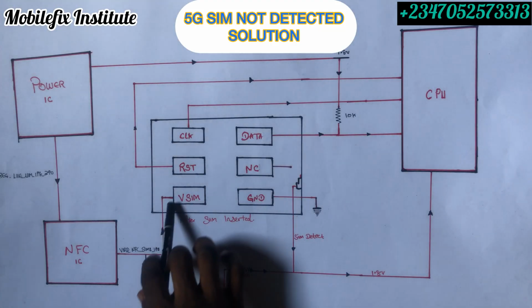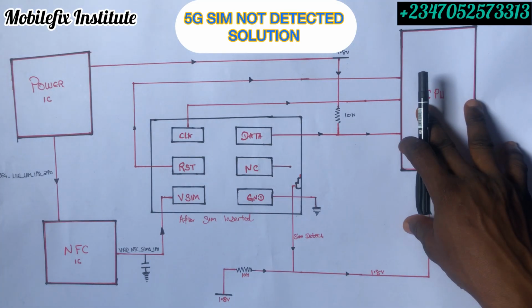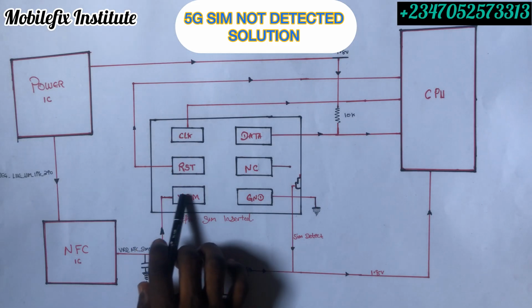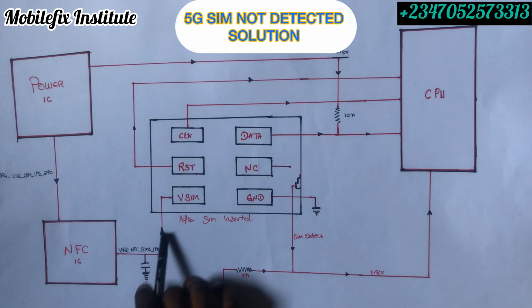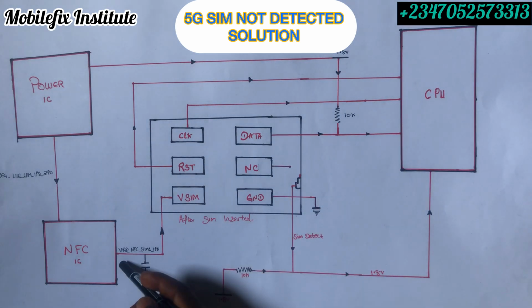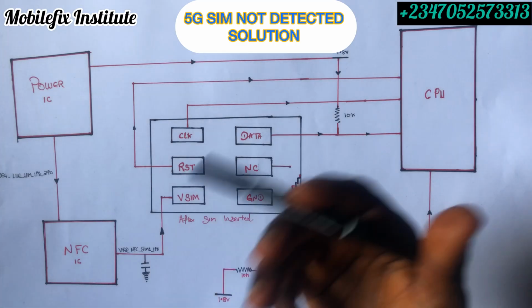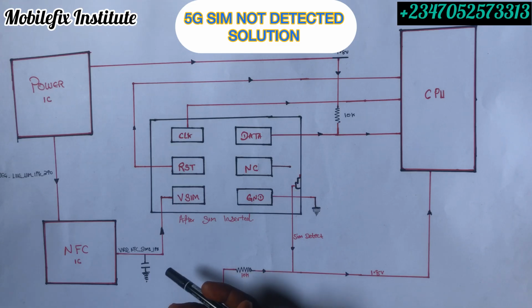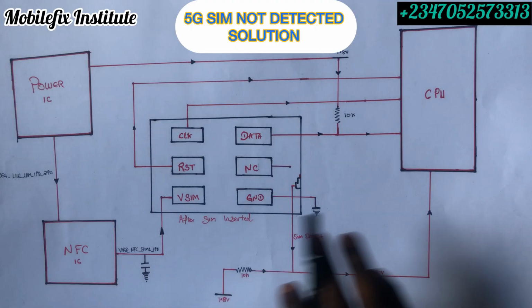So this is our input voltage for SIM1. The NFC IC will also give another input voltage for your SIM2. Okay, so this SIM1 is 1.8 volts. So now the NFC IC inputs 1.8 volts to this pin. You also have to test this pin to see if you will get this 1.8 volts. It is possible for you to get diode readings when the phone is not switched on. You get your diode readings, but after switching on the phone, you might not get this 1.8 volts, maybe because of a faulty NFC, or it's not generating the voltage. So it's possible.